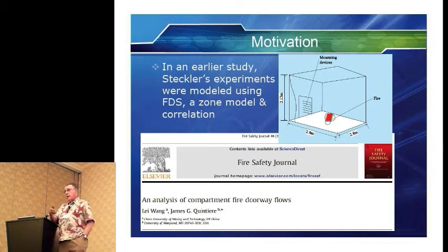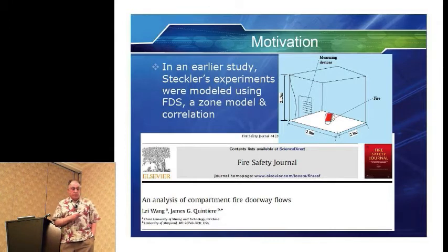And these bumps are actually calculated by Howard Bauman in an inviscid model. So this flow through the door is almost inviscid Bernoulli flow. And if you know the temperature on both sides, that's what these experiments basically proved. If you know the temperature distribution on both sides of the opening and the flow coefficient for the opening, you can predict the flow quite accurately.